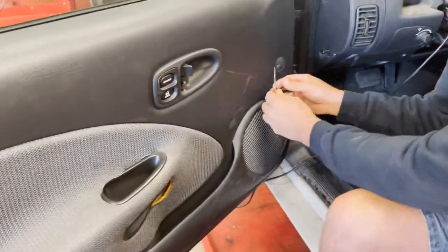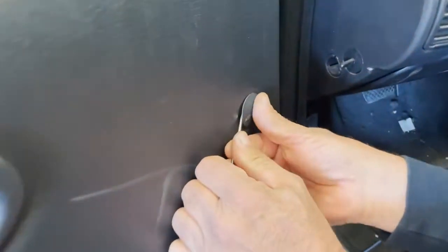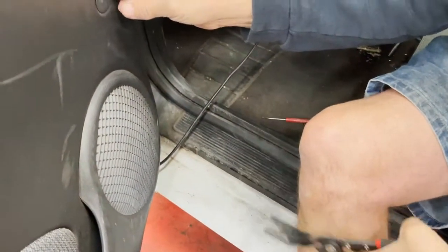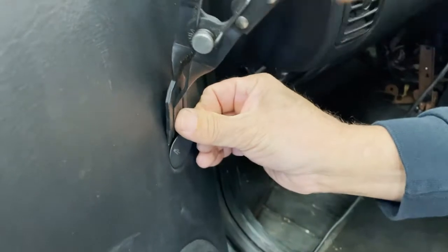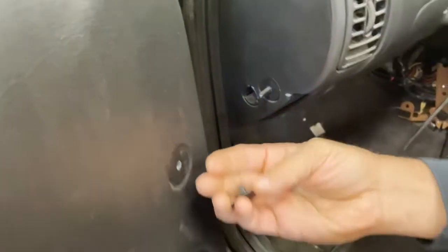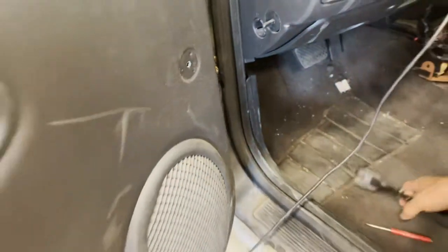So I know there's some kind of fastener underneath here, and I'm going to really carefully get the tip of my screwdriver under there and wiggle this off, and even use my fingers in there until I can pop this out. And it looks like I might need this tool right here. Get that under there. Again, you've got to be real careful that you don't damage anything. And that pops the clip off without breaking it or damaging anything on the door.